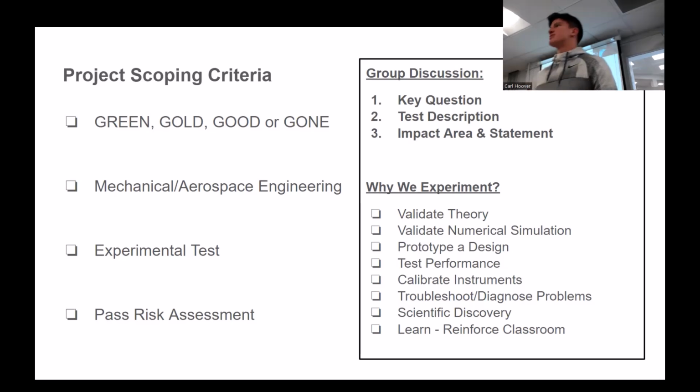So what we picked was studying aircraft flutter, which is basically oscillating wings during certain aerodynamic conditions. So the test procedure was probably going to take a model aircraft, put it in one of the wind tunnels, observe when those patterns happen and at what angles of attack, what air speeds, and that kind of deal, and then try and develop structures that help prevent it. It's mostly a social benefit because it keeps aircraft safe.